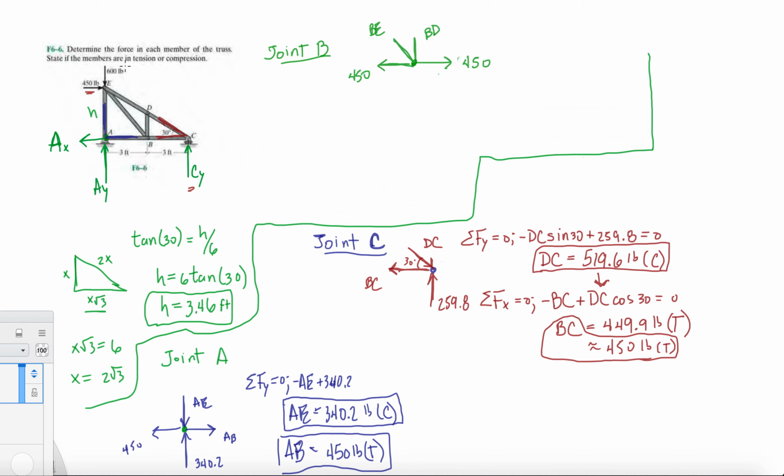If we were to find that angle that BE is making with the horizontal, let's call it theta, and let's just assume that it's going in tension. And let's say BD is going in tension, because I really don't know any of those. If you already know your zero force members and you can analyze it quickly, then go right ahead and you know that those are going to be zero. But we're going to prove it anyways, just to really go through the math.